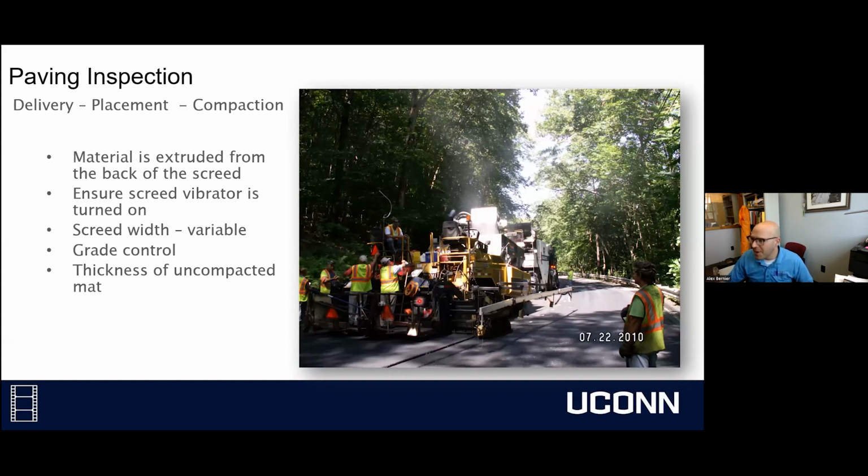The other thing worth noting here is we've got a notched wedge joint being constructed. So we're going to talk about that in a couple slides as well, but it's really important to note that. And with the mobile reference beam, as well as the toe point, we can be adjusting the thickness of our mat. So the same paver can pave 5/8 of an inch thick. It can pave 8 inches thick. It depends what you set your screed at.